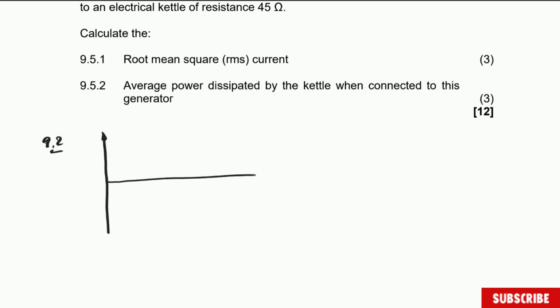So this is going to be the axis. This is time, this is EMF, and EMF is in volts. They don't want numbers, they want the sketch graph here. So when you draw the graph, be careful. I'm going to draw a sine, but you can also draw a cosine. I'm going to draw there. This is roughly drawn, and this is 1 cycle there.